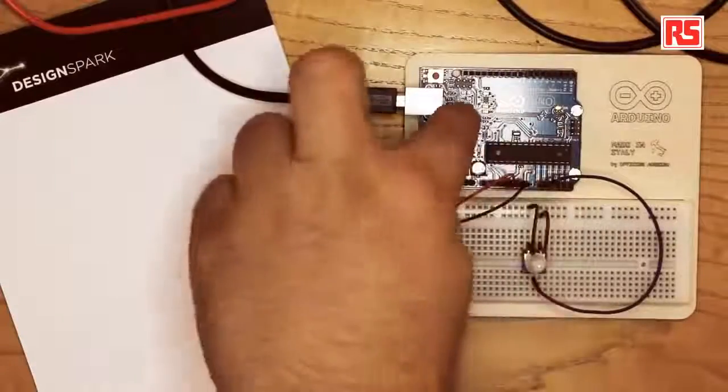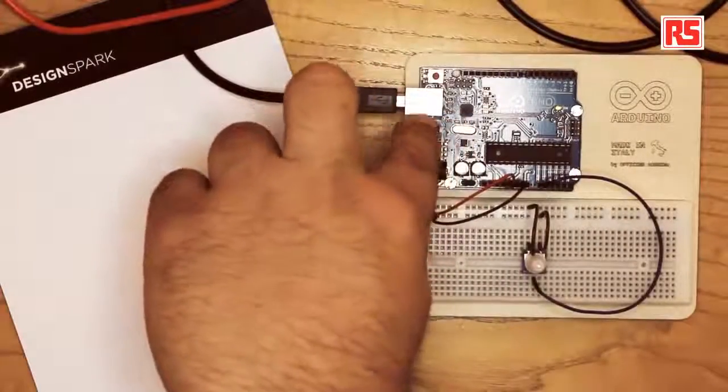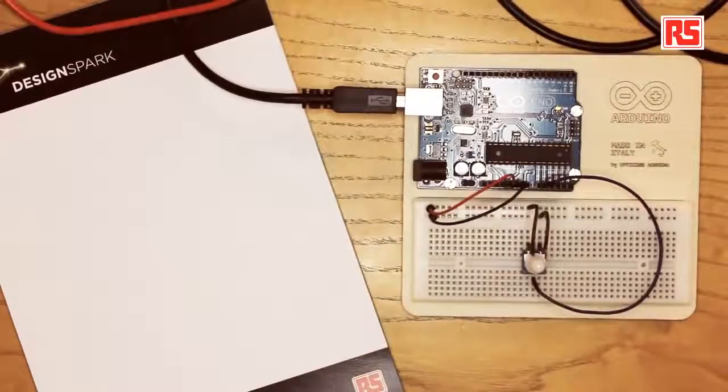For this project, we're going to be using something called serial communication, because the Arduino will send data over to the computer 1 bit at a time at a certain speed that we will define in software. Then the square chip that you see here will convert that into USB data that travels over to the computer.